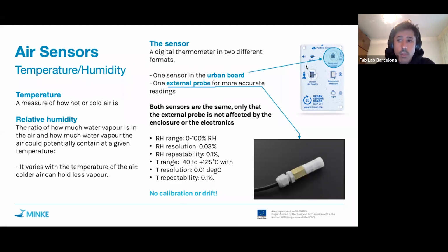These temperature readings will be affected because the electronics will be generating more or less heat, and of course, the sensor will read that. It's our job to calibrate for that, and we have performed calibration in all the different scenarios, but no calibration is perfect. You have to assume that there's probably a little bit more error or offset in these readings versus an external temperature probe.